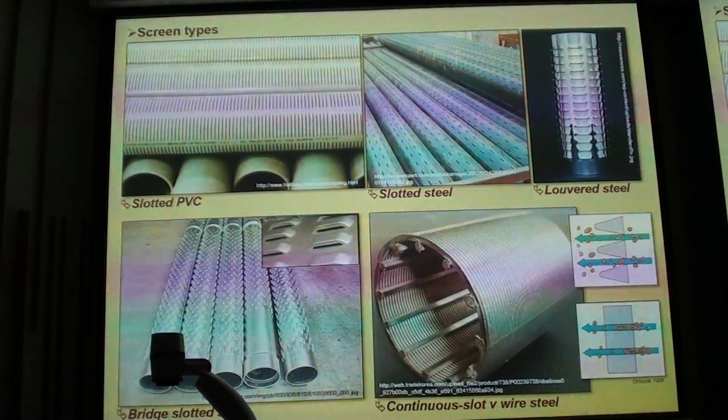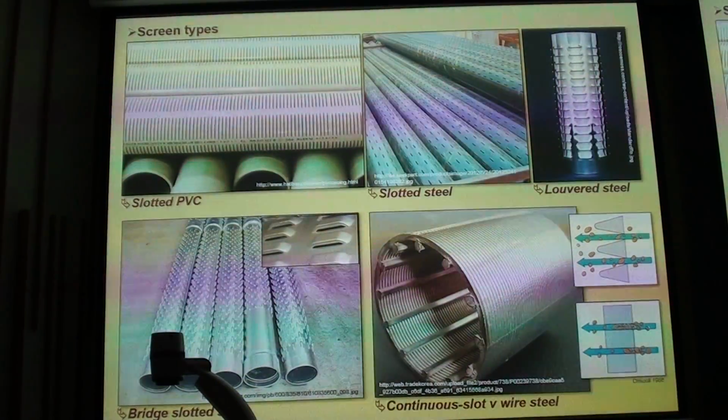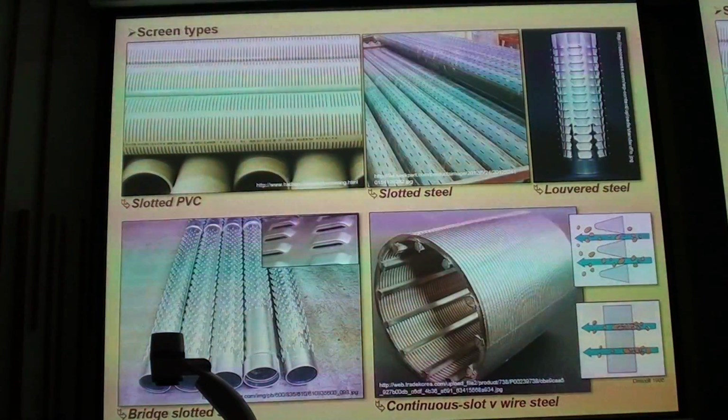So if you've got cylindrical sided slots, then they can quite easily gum up, and once they gum up, you've essentially written those off. If they're not porous anymore, you're not getting water flowing through them. You don't want that to block, okay? You want to make sure your screens can operate cleanly for as long as possible. You can take screens out during the operational life of a well and clean them or replace them, right? But you don't want to have to. It's expensive, and you have to shut down your wells, so you've lost your water supply, etc., etc. So the best you can get are these things here, but they're very expensive.